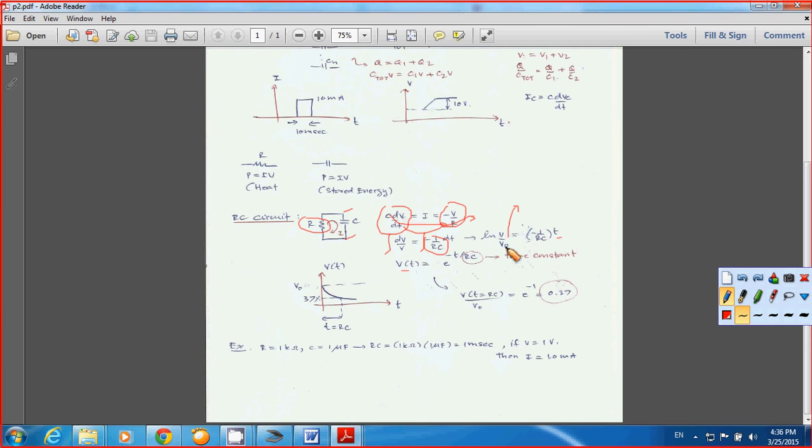You rearrange the equation here and it becomes V over V0 equal to exponential of -1 times t over RC, right? And then you simply multiply the exponential term with V0, and you end up with V0 here. Sorry, I was missing V0 here. And this RC, we call the time constant. Of course, as I told you before, the exponential has no unit, so your RC has to be the same unit as the time, so RC is going to end up with the unit of seconds. RC becomes the constant.